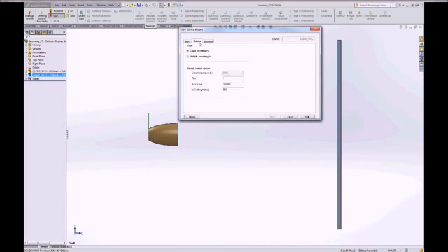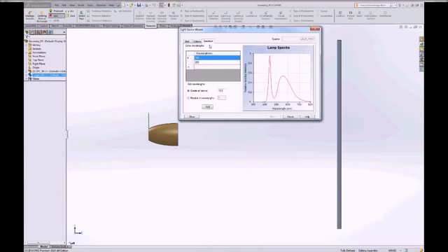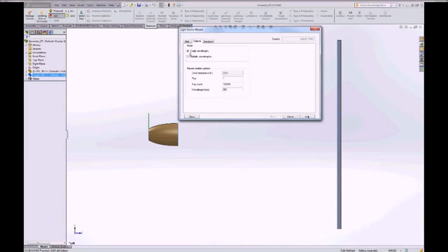In this particular case, since we don't have any refracting components, I'm not worried about dispersion. I'm going to create all of my rays at one particular wavelength. But if I did want a spectral distribution, I could get that information as well, and we would get distributions of rays that follow the spectral weighting. But again, for our purposes, this will work fine.